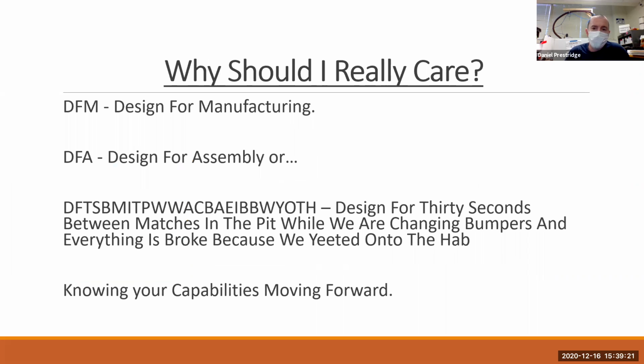So moving on to, why is this a thing? Design for manufacturing, and why I'm trying to bring this up right now is moving into the next build season. You have to think about, okay, what actually do I have on hand? What machines, what tools? If I make something that is some amorphous blob that fits into the design, but you don't have a 4, 5, 6, 12, whatever axis CNC, you don't have a 3D printer, you're not making it.